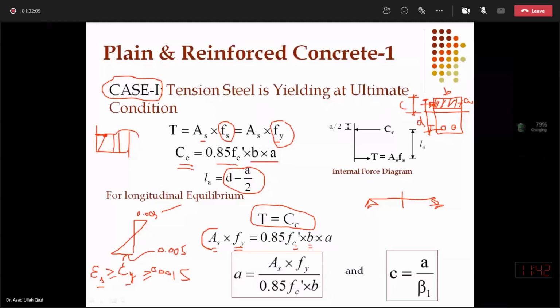I will also know what is the grade of the steel used in this project. In general notes on the drawings, I can get the details about the material strengths, fc prime, Fy. On the cross section, I can get details about the section width and gross depth and effective depth. So each and every detail is with me